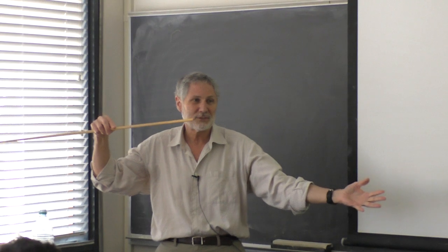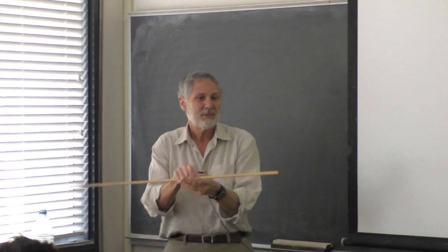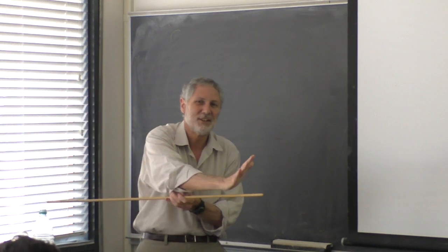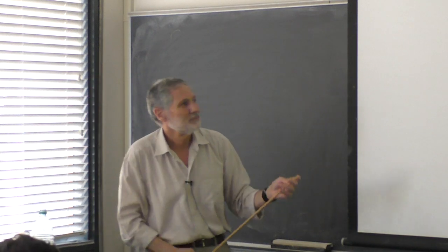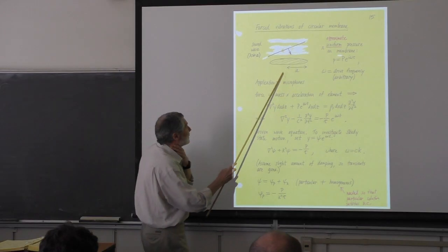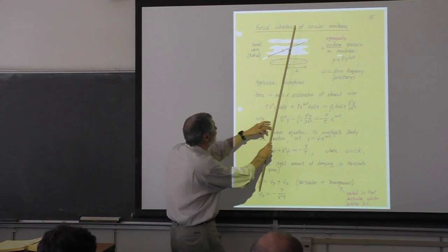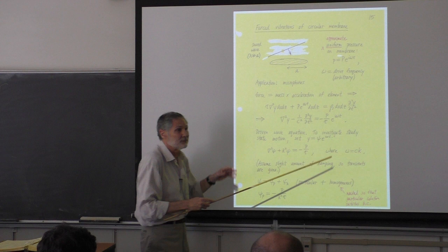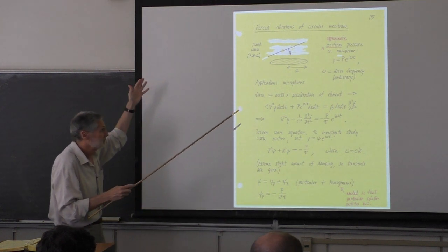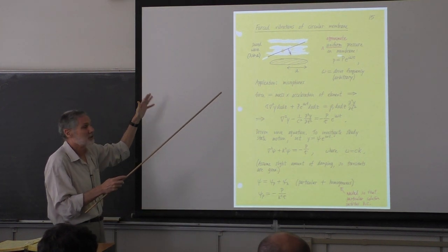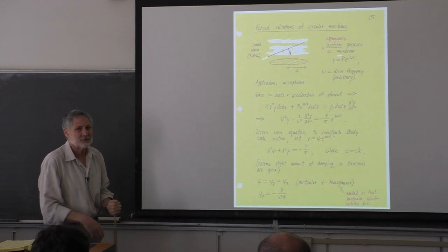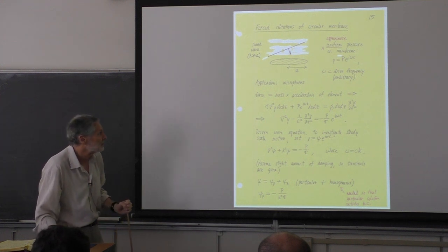As long as the wavelength is large, it'll pick it up even back here, okay? It'll pick it up fine. Now microphones are corrected for this angle right here. If the wavelength is not sufficiently long for you and you want to correct for it, there are corrections. You can see these in specifications of the microphone.